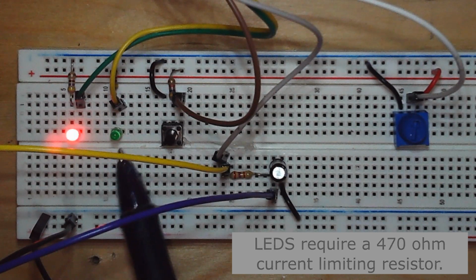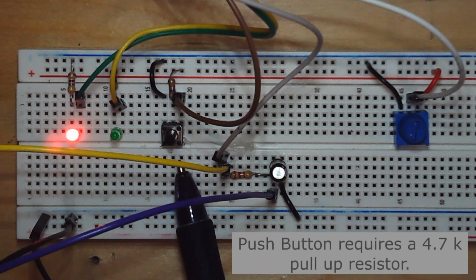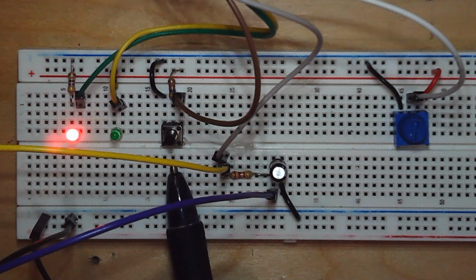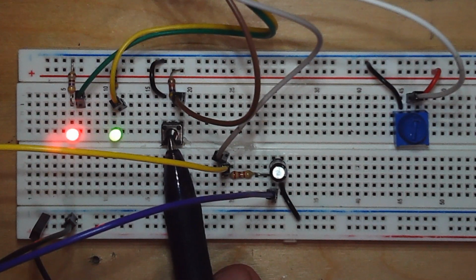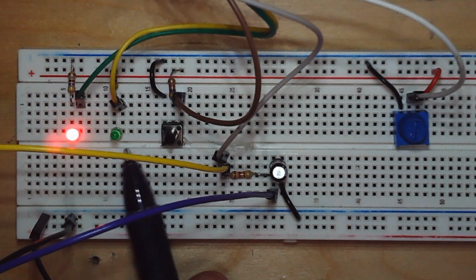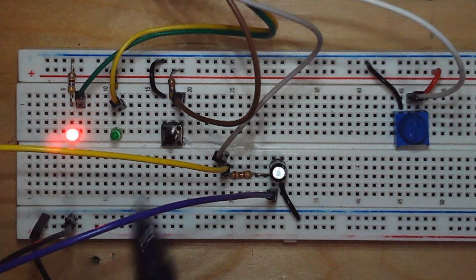Same thing for the green one. Here is a push button. One side of the push button is connected to ground. The other side has a pull-up resistor, which then goes to the input. So when the switch is open, we've got a logic high. And when you close the switch, it gets grounded, and that's going to let the software know that the switch is closed. We're testing for a logic low, and then it turns on the LED.